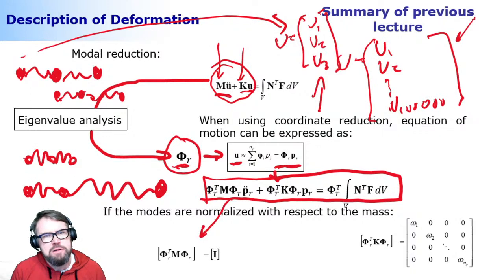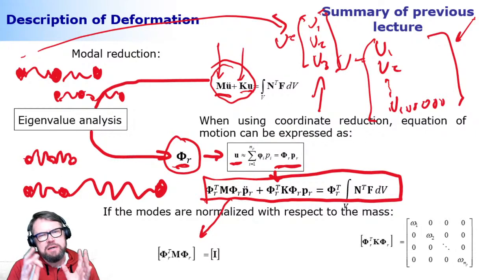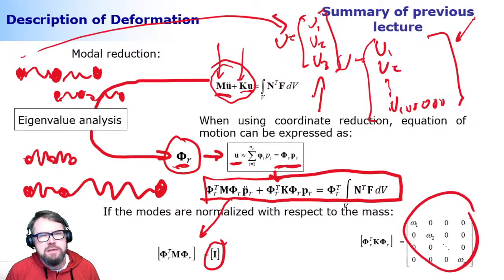And because they're all independent, I can solve one modal degree of freedom knowing nothing about the others. You cannot do that in finite element modeling, because there you have the block diagonal representation of stiffness and inertia. But when moving to modal degrees of freedom, you do have that freedom. So you will have a diagonal representation of mass and stiffness. So that's how it goes.